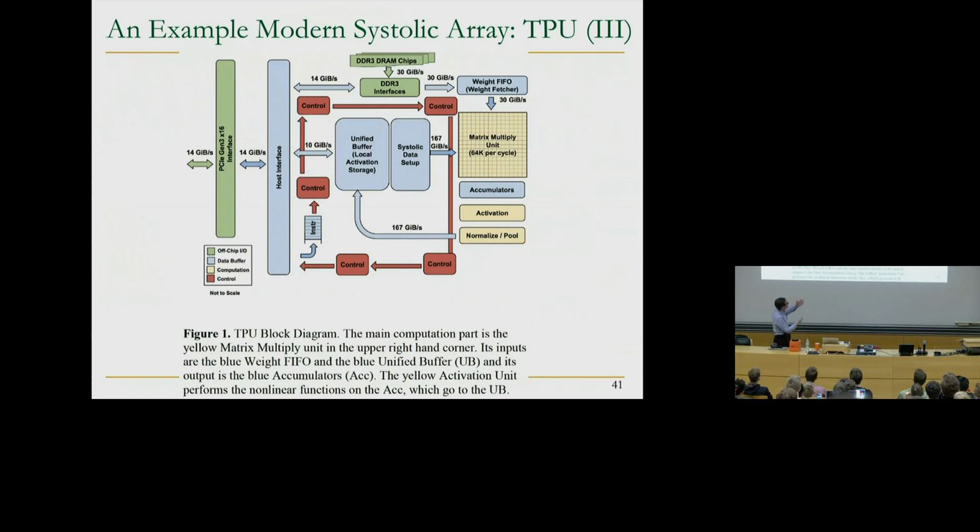And a systolic array enables a large number because you're actually operating many units in parallel at the same time. But to be able to make use of it, you need to actually design a system that takes the algorithm and pushes the algorithm data into this matrix multiplication unit. So it's not just this matrix multiplication, it's not just the hardware, it's really the system itself. How do you actually take the algorithm? How do you do the buffering of the data? How do you set up the data?